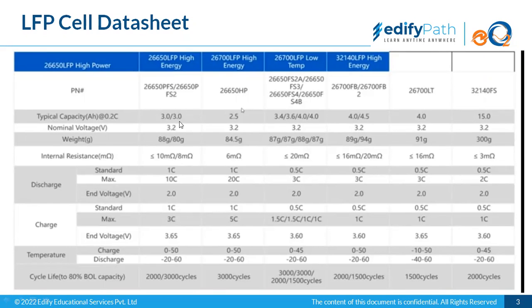If you talk about the holding capacity of an LFP cell for the same geometry, it would be a bit lower than the NMC cell. So we would be able to withdraw lesser energy from an LFP cell in comparison to an NMC cell, because their operating range around the nominal voltage is a bit shorter. That is more for safety concerns and safe levels. They have kept the energy retaining capacity, and what we can withdraw from the cell, a bit lower than a normal NMC cell.